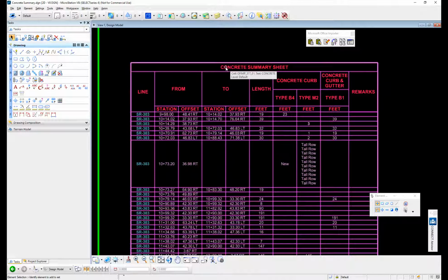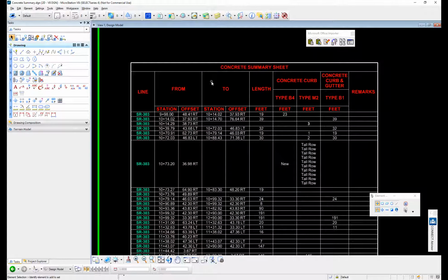But so what? Those aren't all the problems with linking. The big problem with linking, or one of the big problems with linking, is updating. How do you know if this import needs updating? Well, frankly, most of the time, our users don't want to worry about it. So whenever you open this DGN, we'll automatically update the information in here from Excel if somebody has changed the spreadsheet. So if the spreadsheet has changed, we update the DGN when you open the DGN. Automatic, fast, don't worry about it.